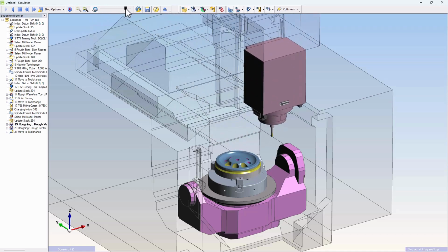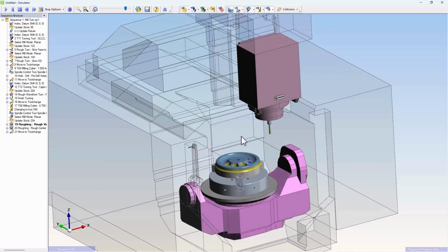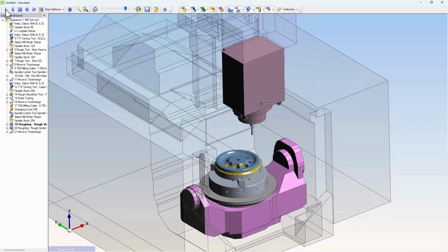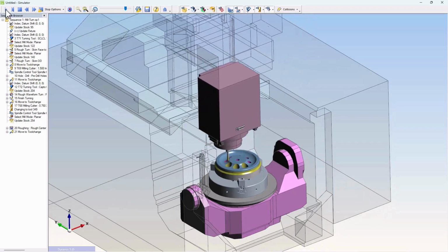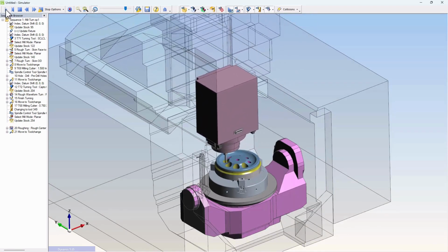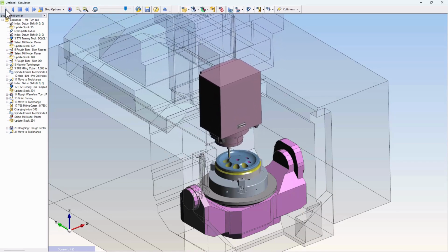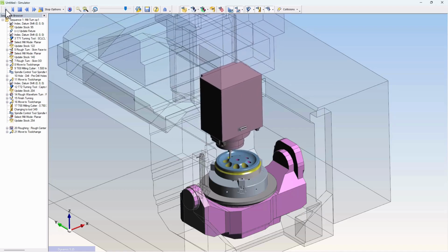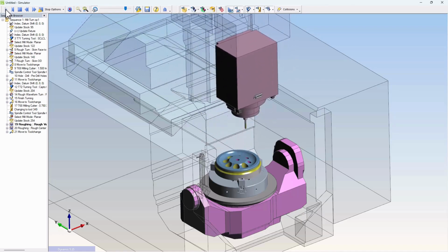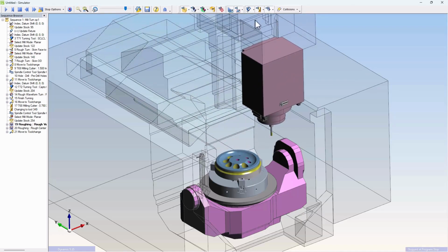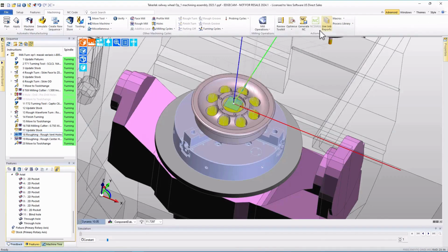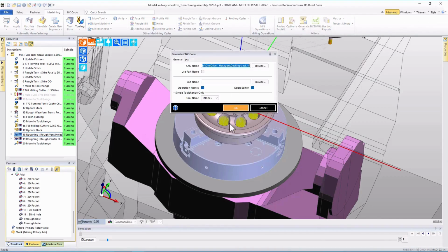We've reached 30 minutes, retract away, and notice it comes out to the coordinates that we requested. Perfect. Play, resume, it comes right back into the area, intelligently re-enters the material, resumes cutting, again out of a single program event or cycle for convenience in EDGECAM, then program stop, and after, if I play it again, we'd resume.